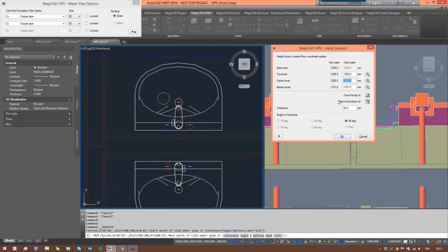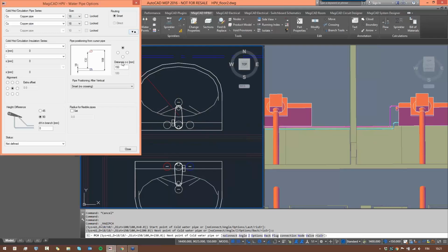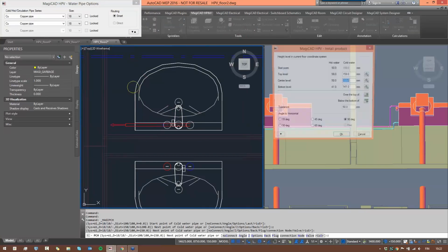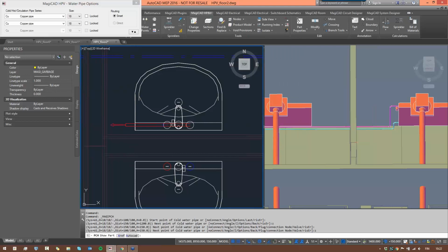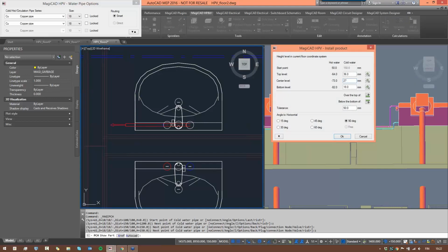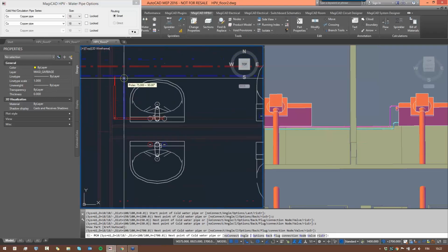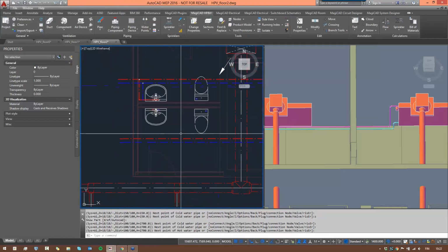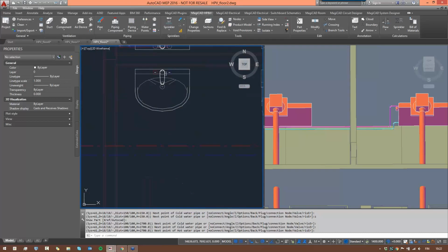First we want to go down. We are defining the cold water pipe there. I'll put it on 150. And make sure that there's 100 millimeters between the two pipes there. And let's see the height level from that one. That's 2.8, so let's put it on 2.7. There. Yes. Good. Nicely done there.